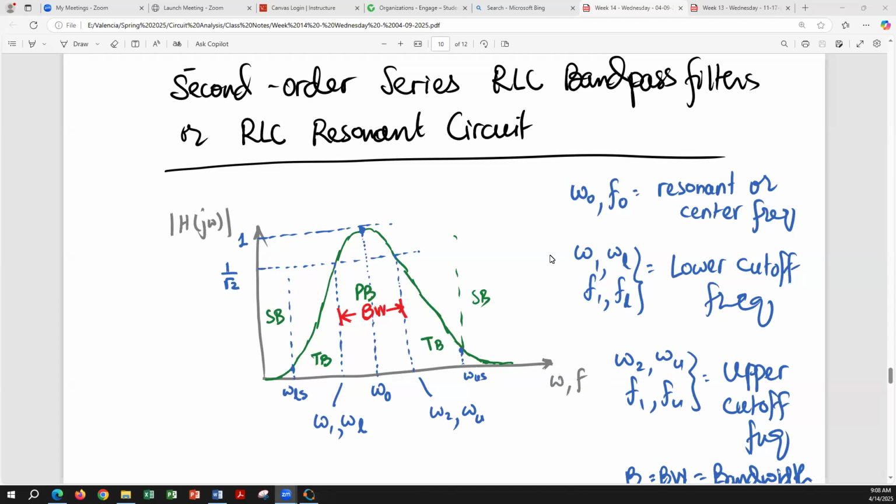You have a pass band, where the filter lets through the information that is coming at its input. And then you have the transition band. The transition band is supposed to be as steep as possible, such that the frequencies that we do not need don't go through. For the ideal filter, your bandpass response is simply something like this. So this is your pass band, and then you have your stop band. There is really no transition band in your ideal bandpass filter.